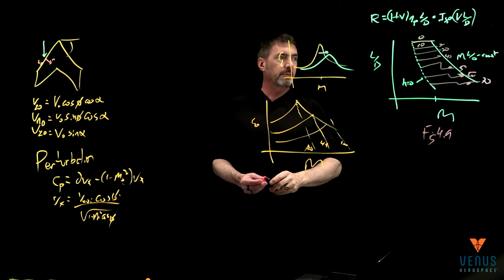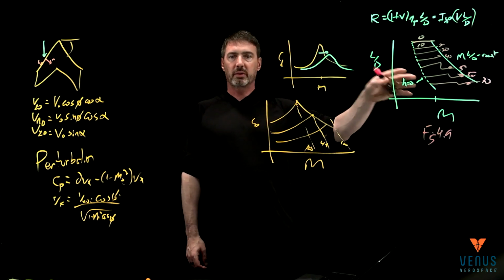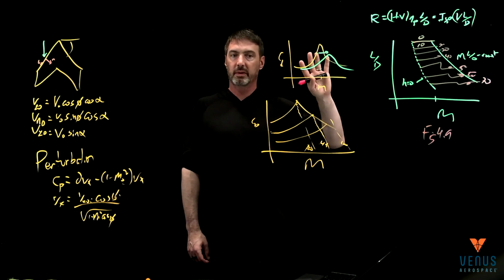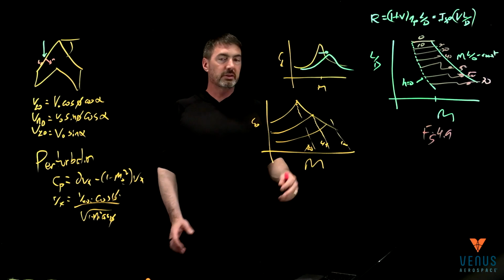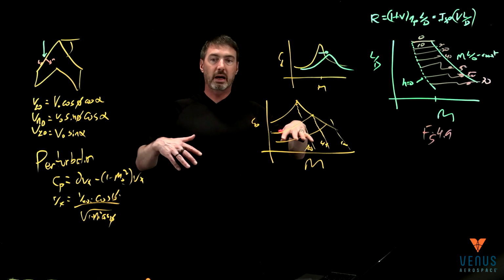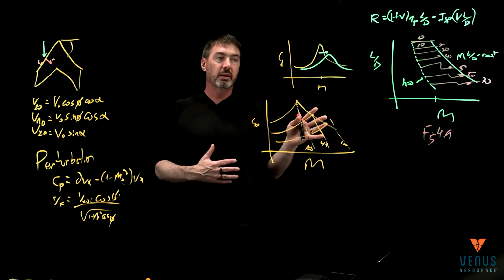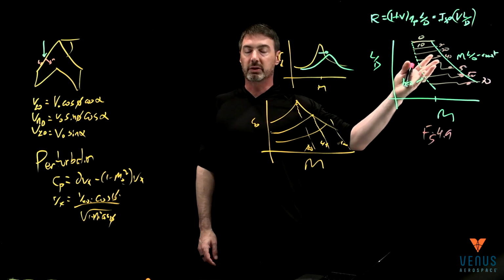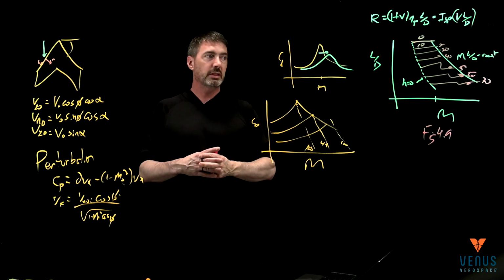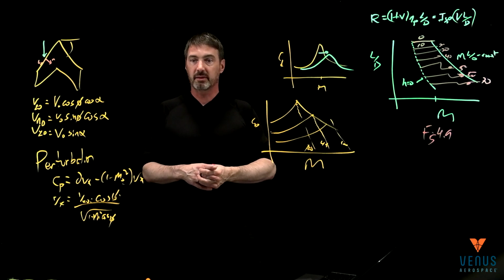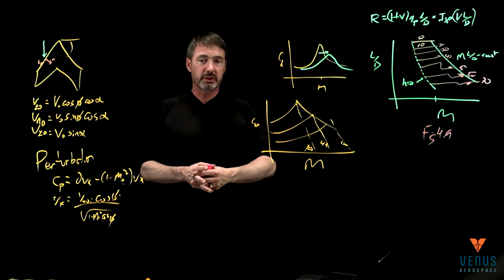So what it's already showing, and these are real plots from, not necessarily analytic, but from real system designs, is that you're seeing pretty clearly how the slender swept aircraft is getting into the same regime as what we're used to from a range point of view. So this is showing that really around Mach 2, there should exist something that has roughly the same performance. And we saw that with Concorde,